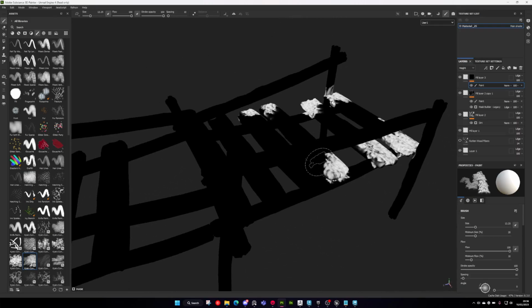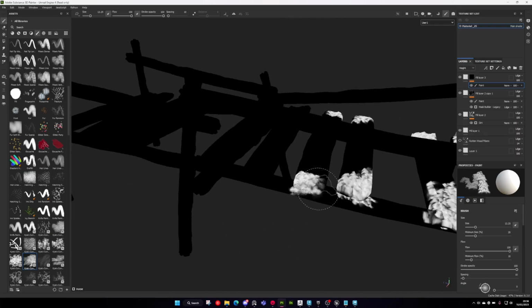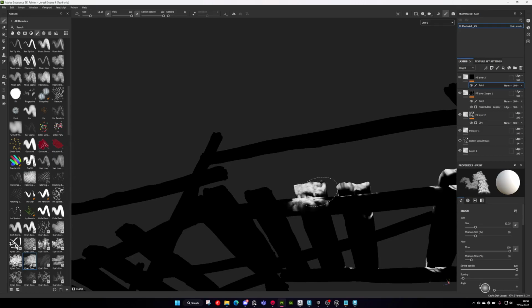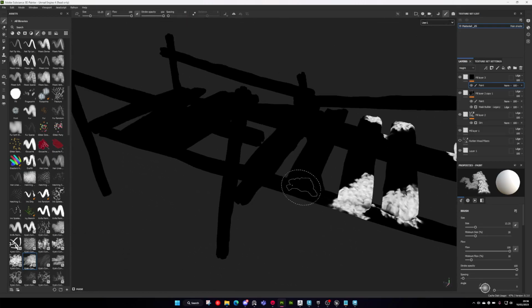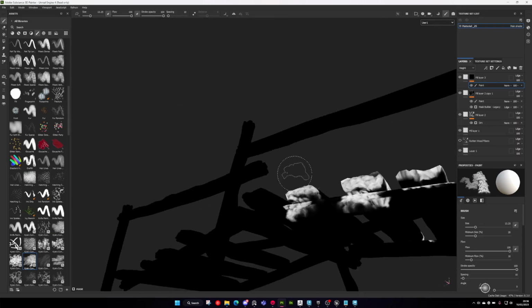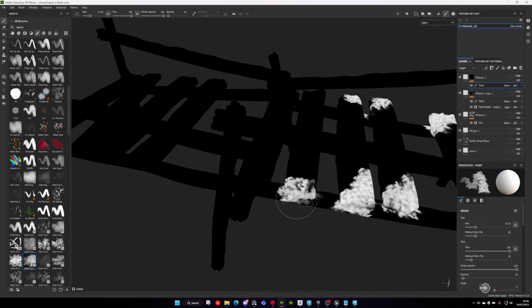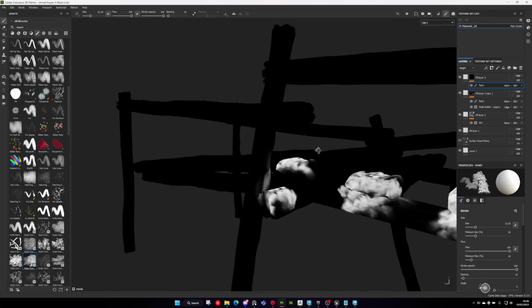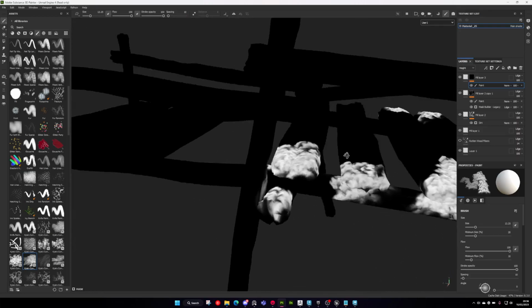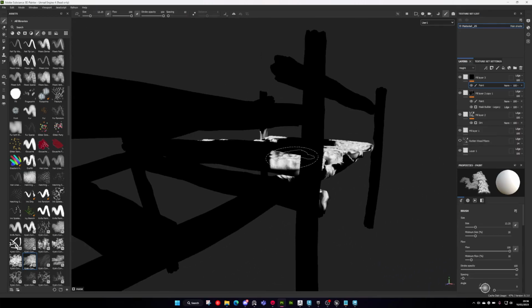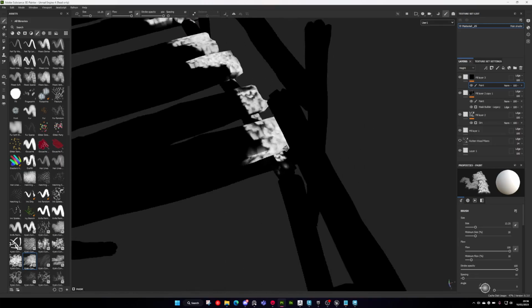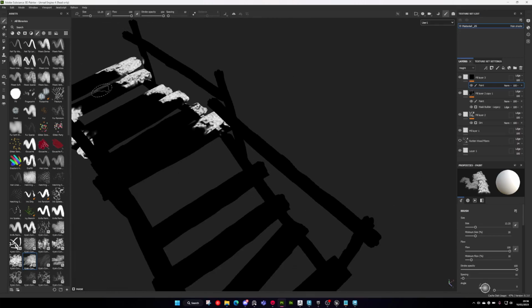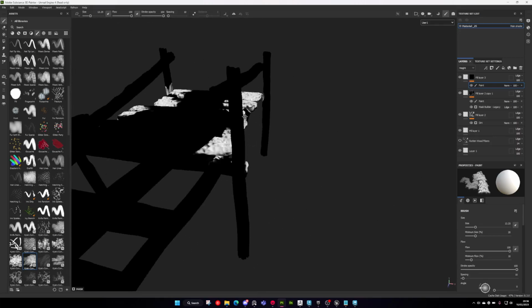So with these masks, you can control kind of anything you need in Unreal. You're not just limited to controlling the color. You can use these to control the roughness values, metalness, emissive, stuff like that. So this can be another use of what you do. So we could probably do a third mask being like wetness. If we wanted some wet streaks going across this, that would be a good example of what you can use.